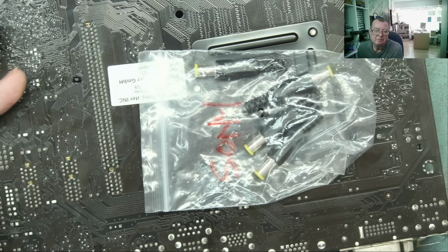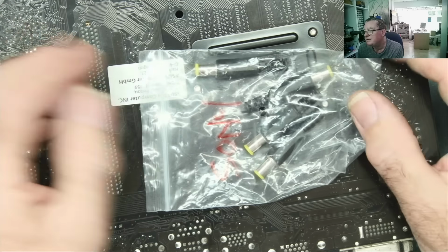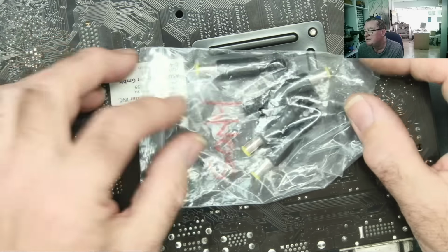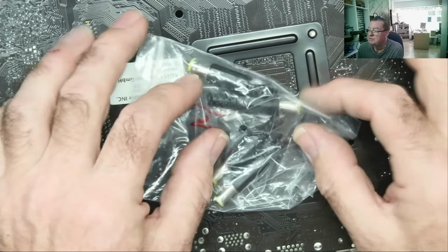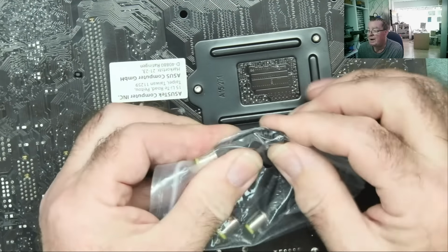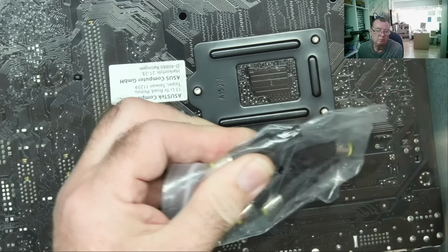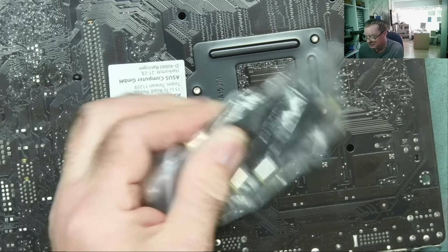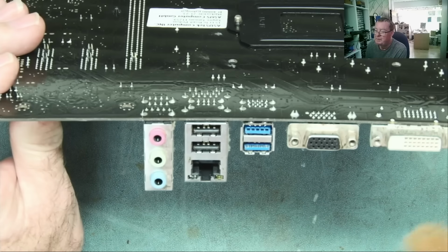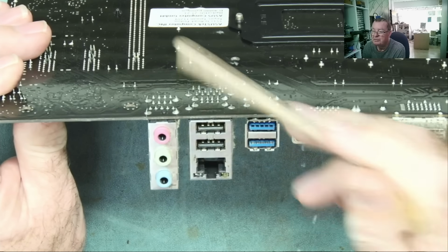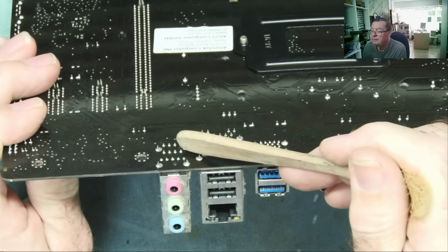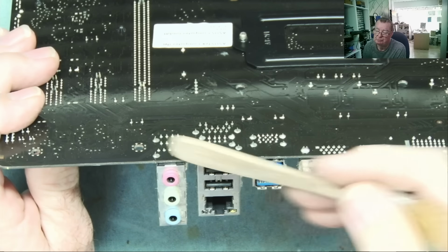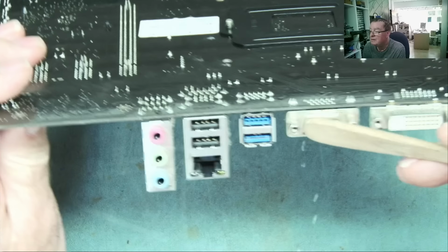Again, if the device is being plugged in and unplugged on a regular basis, you'll very commonly find that there's a dry joint on the connection between the socket and the PCB, and sometimes a fracture in the wire where it comes in just because it's been plugged and unplugged many times. Metal fatigue will set in, so that's a very common failure. On the same basis, not only coaxial power connectors, but jack sockets: corrosion inside them, fractured joints here, or problems with the actual jack plug where the lead's connected to it.